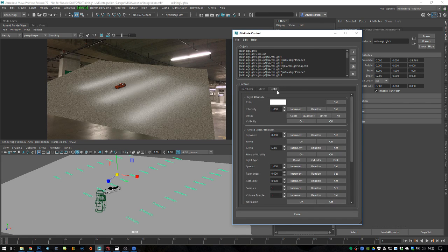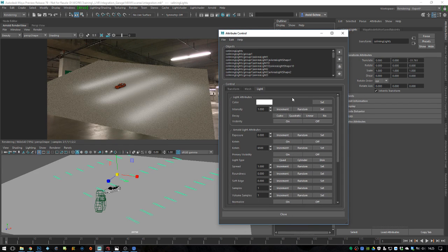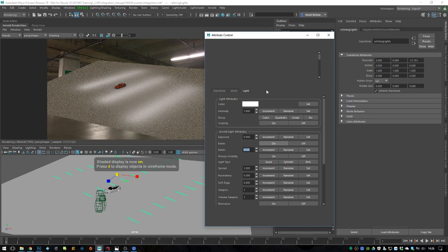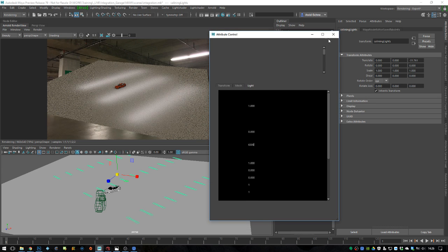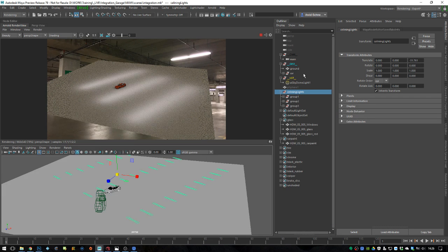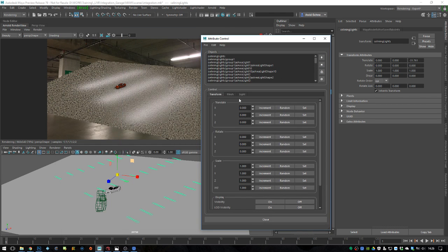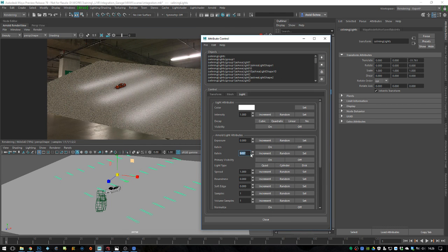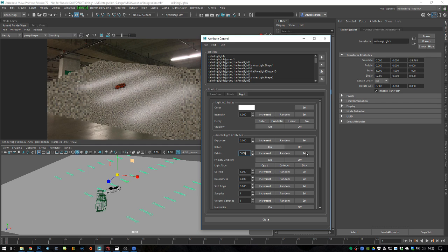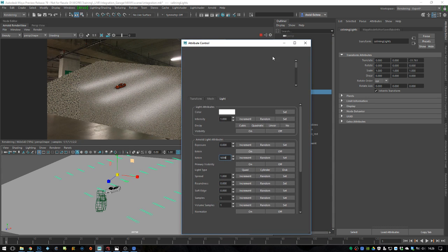So now you can actually go to the light tab and you can change the light color. You can add intensity. So let's bring in some Kelvin color to this. So I enable Kelvin, and let's say we want a warm color. So we change the Kelvin to 5000, or not. This is my UI bugging out again. Let's try it again. Yeah, I don't know. Now it's working. Enable Kelvin and set it to 5000. And now we should have a warmer.